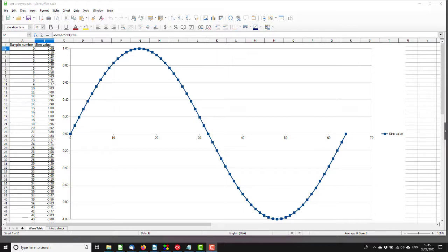To get some idea of the noise introduced from interpolating a sample to generate different frequencies, we're going to look at the simplest possible waveform, a sine wave. We'll look at more complex waveforms in the next tutorial when we come to look at the oscillator design in detail. In this case, our sample actually only needs to be 1 cycle long, because when we get to the end of it we can round back to the start again. I'll describe how this works in detail in the next tutorial. I tend to refer to these single cycle samples as wavetables rather than samples.